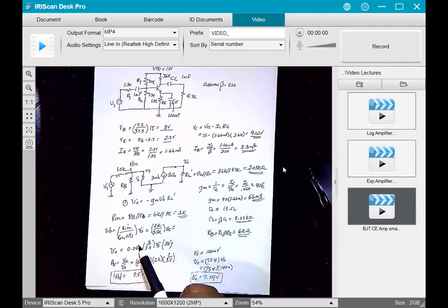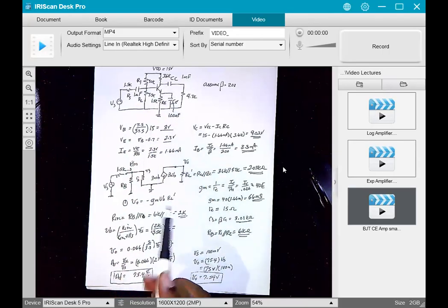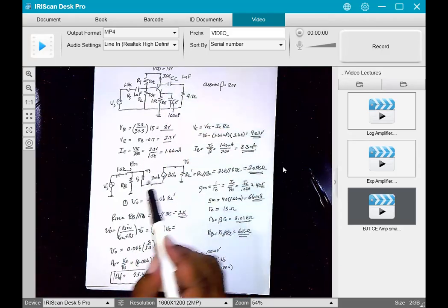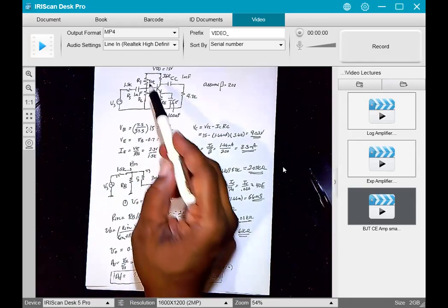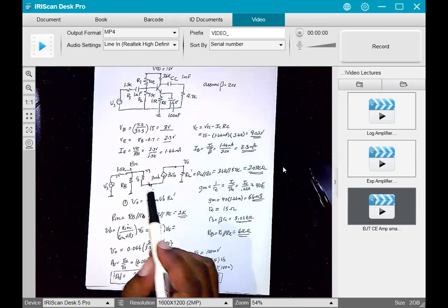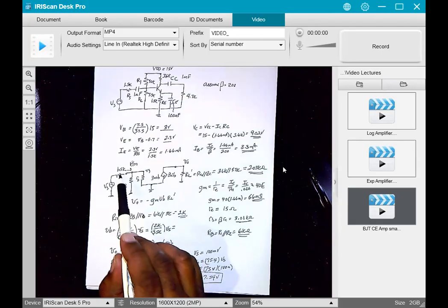In electronics 1, when I taught it, you would have to design this amplifier so it had a minimum value of input impedance. Well, the input impedance is R1 in parallel with R2 in parallel with RB here. So you would have to choose these values of resistors and choose your currents to give you a large input impedance compared to your RS.